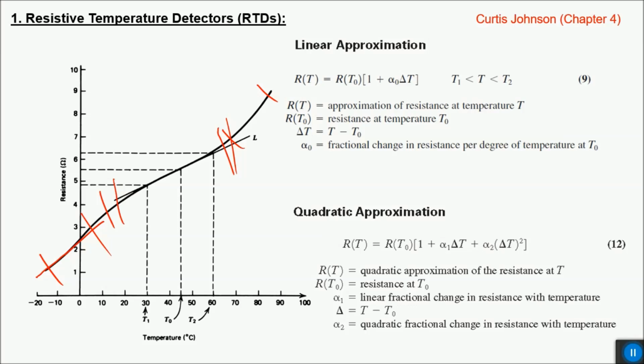So what we are trying to do is to mathematically relate temperature versus resistance of RTDs in general, not for a specific material. If we know the specific material properties, we know the exact relationship of rho versus T, but that would be different for all the metals, for every different kind of alloys and everything. But in general, if we talk about RTDs, we should be able to develop a general formula that would be applicable to any type of resistive temperature detectors.